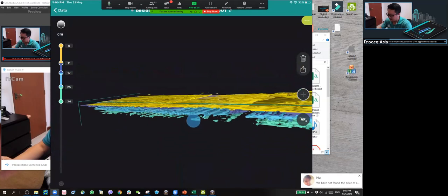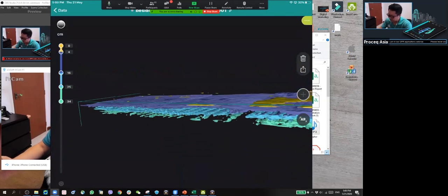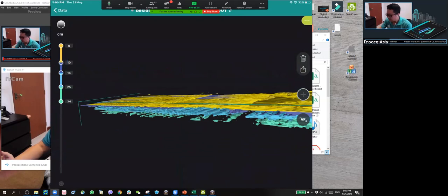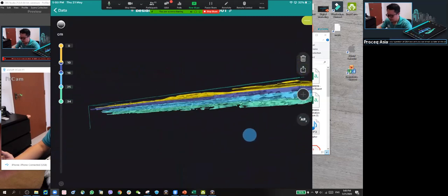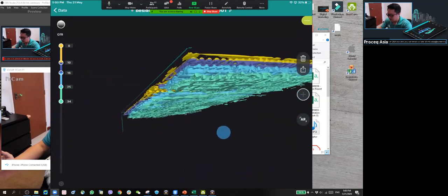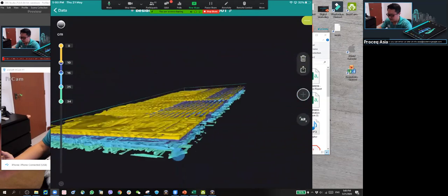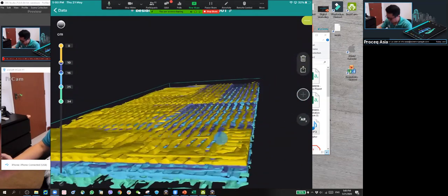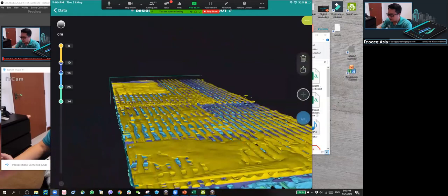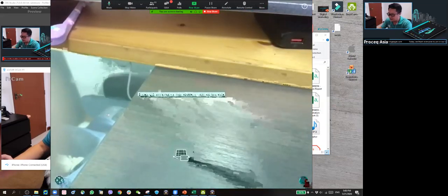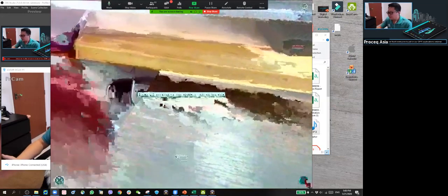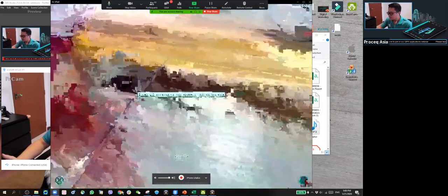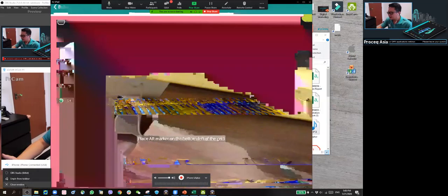Of course, I can adjust the depth of the different color codes. For example, I'm interested to look at the first layer in yellow, the second layer in purple, and later on blue and light green. So this is a result. Of course, if I know where my test location is, I can leave my AR marker, scan the AR marker, and instantly have the measurement result at the test location.